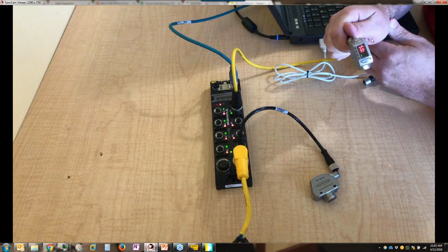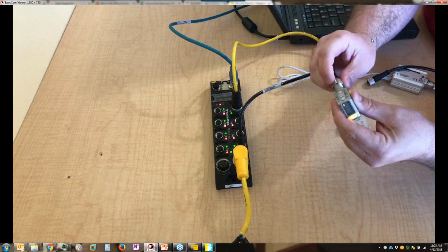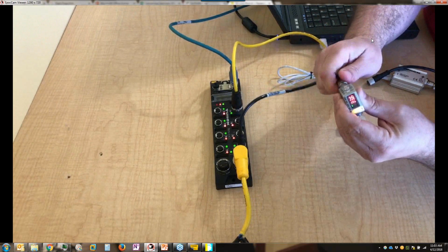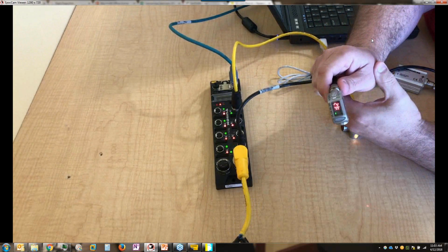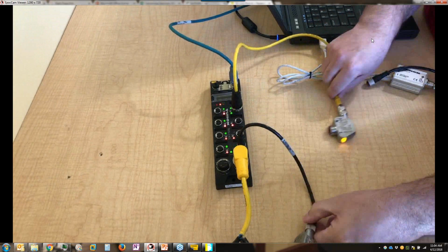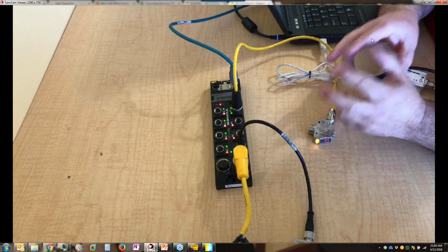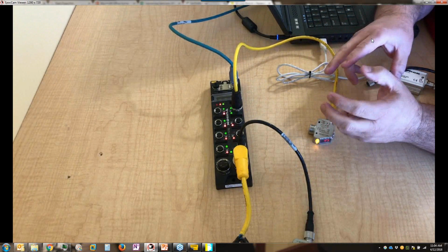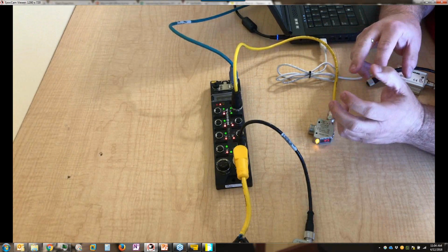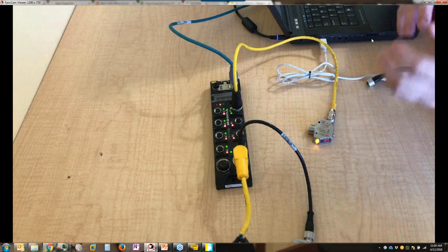And there it is. If I took the one that's reading 175 and put it back into port 1, the master is going to restore to the device, and it should read just 150. So by doing this a couple of times, I've been able to demonstrate to you the simple sensor replacement capability using IOLink technology. This is a big game changer, and for this reason alone would be compelling evidence for you to investigate using IOLink technology in your applications.